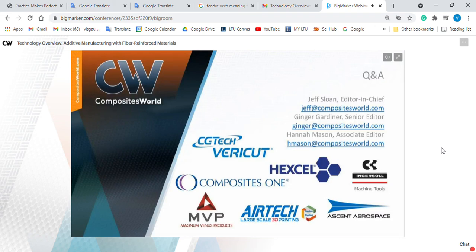In terms of sizing or surface treatment, typically you do not treat or size fibers for use with thermoplastics materials, although there is some research exploring sizings for thermoplastics that might change that. If you are additively manufacturing thermoset materials, that might be a different situation. That's not something we've explored yet, but a company like Continuous Composites would certainly be able to speak to that a little bit more. They're the ones who use thermosets.